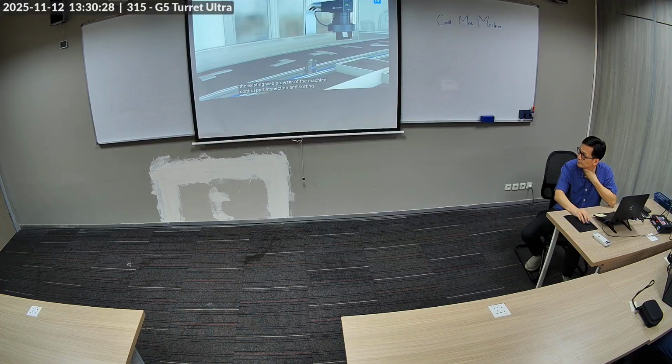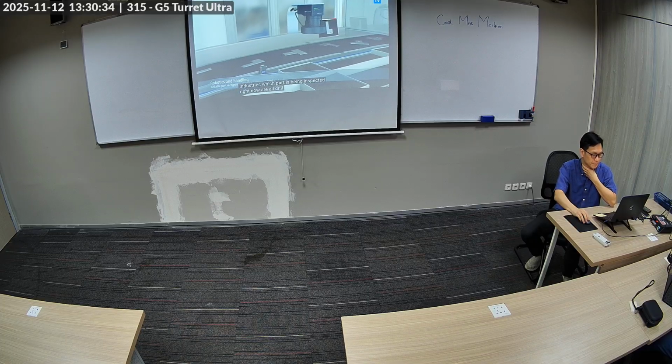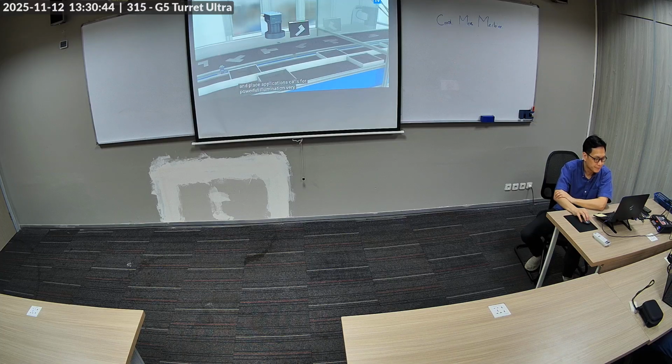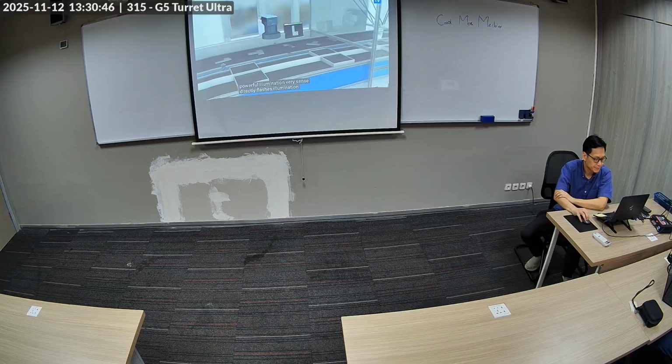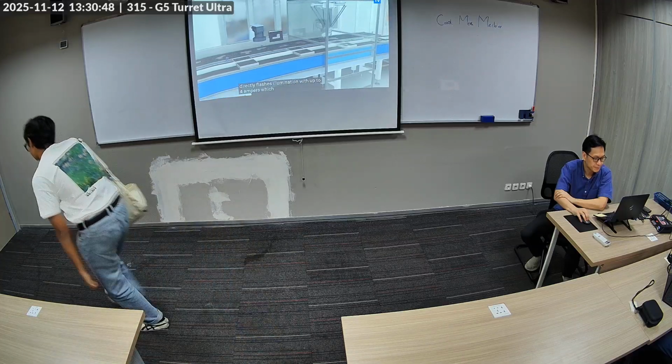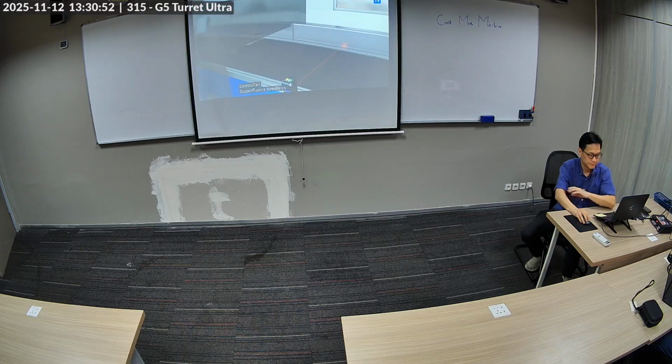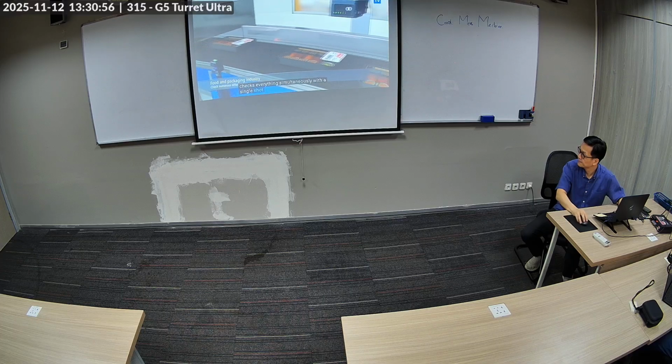Part inspection and sorting is an everyday occurrence in most industries. Which part is being inspected right now? Are all drill holes present? What is the part position? The typical rather large working distance in pick-and-place applications calls for powerful illumination. VeriSense directly flashes illumination with up to 4 amperes, which makes any external flash controller superfluous. Needless to say, VeriSense checks everything simultaneously with a single shot.